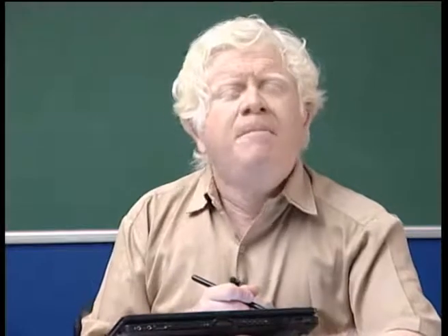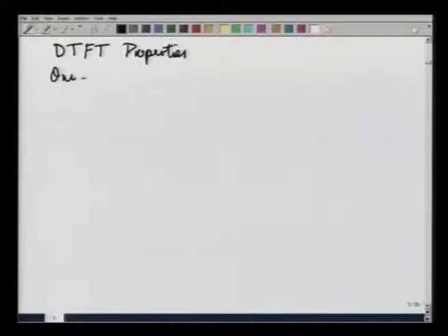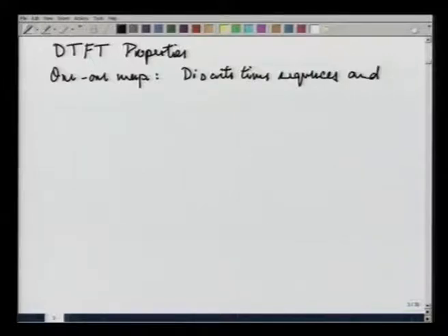Next item on our agenda is to explore the mathematical properties of the DTFT. Fundamentally, the DTFT takes infinite discrete time sequences into periodic continuous frequency functions. It is a 1-1 map between discrete time sequences and periodic continuous frequency functions.